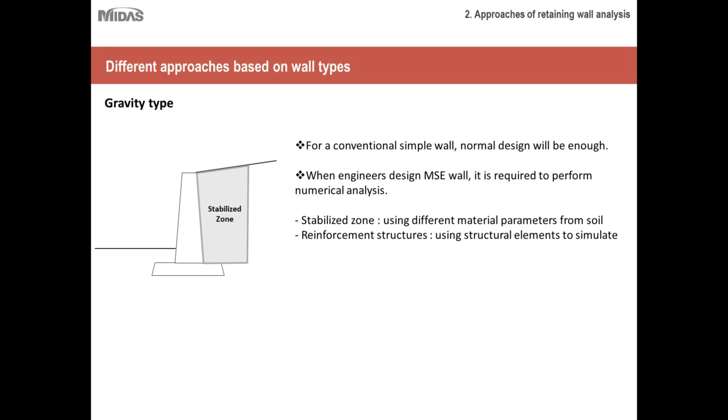Since the MSE wall in itself is constructed as different modules put together in stacks, so basically it is a segmentally constructed structure, you must consider its actual construction procedure, and at the same time you must use proper element types in order to simulate the same behavior.